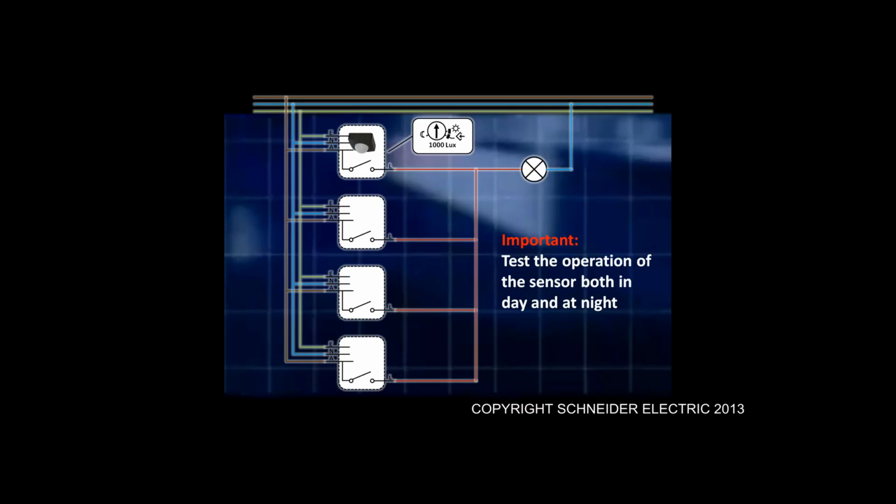Now for night mode, you can either come back that night, or if you have the facilities and means to do it, cover the sensor head. Wait for it to time out, because you'll probably find that the light will come on. That is a normal function: when it goes into what's known as night, it will turn the lights on for a predetermined amount of time. After such period, wait till it times out, then while keeping that cover, so keeping the sensor in darkness, try to trigger that light off by whatever means you have available. Otherwise, if you can't do that, the only alternative is to come back that night when it's dark and test it out then.